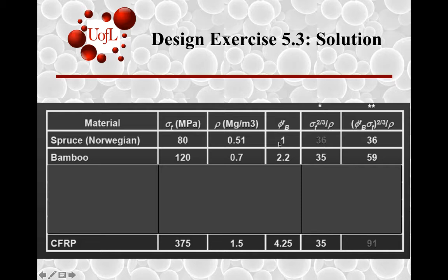In the first case, phi is 1, and so you get the same shape efficiency factor. And then as this shape efficiency factor doubles, roughly, this is about square root of 2 times. And so same thing, as it quadruples, it's almost 3 times that amount. So this gives an idea of the fact that different materials can be created into shapes without buckling to greater extents.